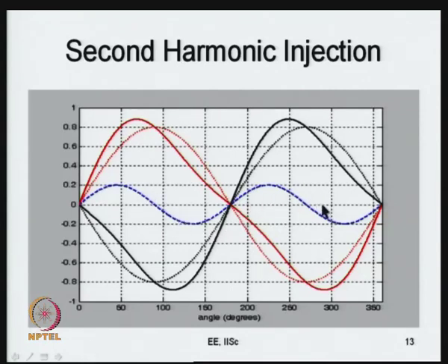So, all I can say is you can add a second harmonic like this of a small amplitude, and you see that the red phase thing increases, the black phase negative peak goes down further. Here again the black phase thing goes further. So, the peak values are going, the modulating signal is no longer quarter wave symmetric. Earlier the sine wave is nicely symmetric about its peak, about 90 degrees, now it is no longer so. So, all this happens, but it is okay, but the final output voltage will be unchanged now. So, there is no point essentially, but nevertheless you can add a small value such that this peak value or this peak value do not go beyond plus Vp or minus Vp now.